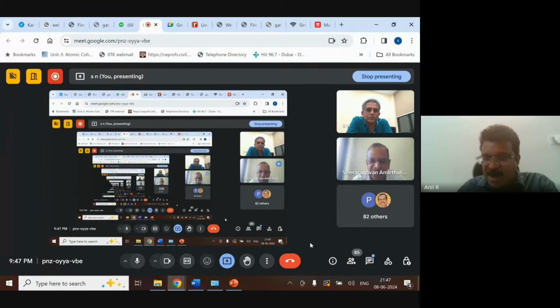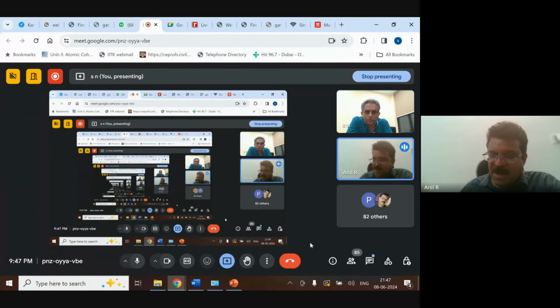Sir, I'll add on to that question. Shyam, when we are doing FDR on old PMGSY roads, they have a crust thickness of granular layer maybe around 250, 300 millimeter. And on top of that, you have a 20 or 40 thick bituminous layer also. In that kind of road, there will not be any chance of getting the soil or the subgrade into that. In that case, do we need to go for an additive, or will simply cement work?